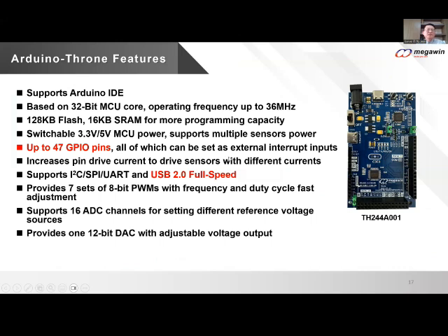So it supports Arduino IDE, and based on 32-bit, like I mentioned, and 128K flash and 16K byte SRAM. Okay, and support 3.3 volt and 5 volt MCU power, and up to 46 GPIO pins, and increased pin drive current and the drive sensor with different currents.